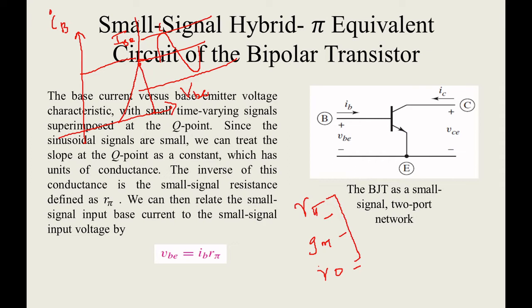Okay, we can see there is the non-linearity, right? There is a resistance in the change of IB with respect to VB. So there is some resistance between the IB and VB part. That resistance is nothing but your R pi. Here it is plotted for IB versus VB, right? That is the reverse of V by I. So I can write this slope. This slope is nothing but 1 by R pi.